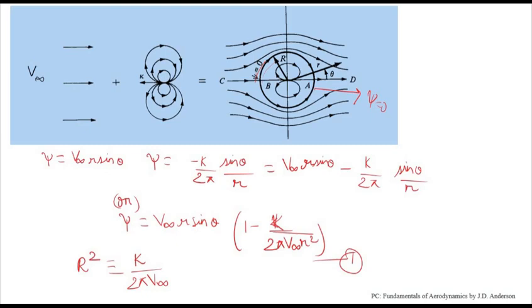So lift is a force which is generated only when there is a pressure difference. Now as we see, there is no pressure difference over here, which means there is no lift being generated. This means I can call this flow a non-lifting flow over a cylinder. Now this was the story of top and bottom. Let us consider the front and back. The front part, that is this area, and the behind part.